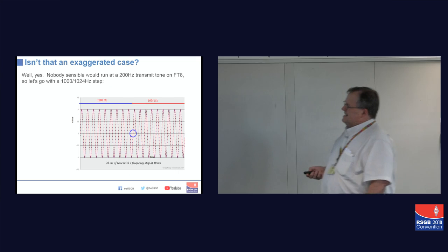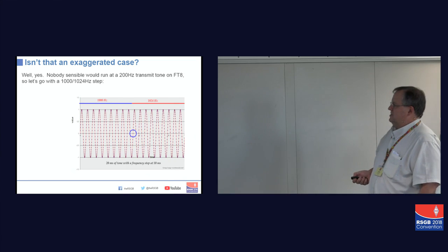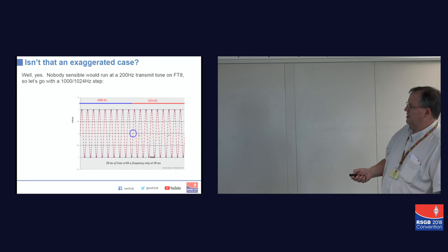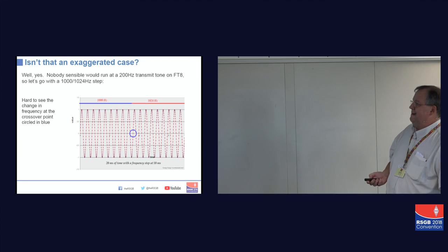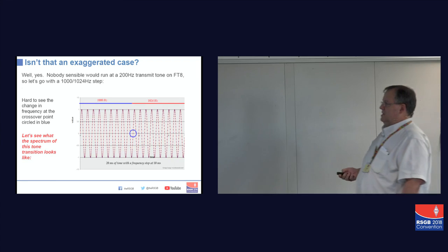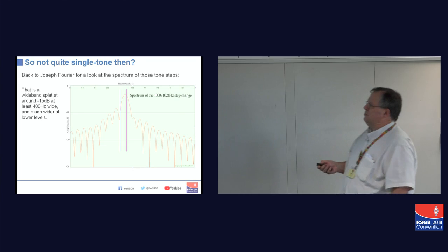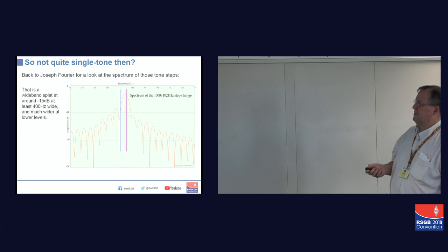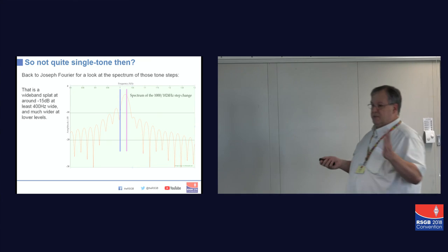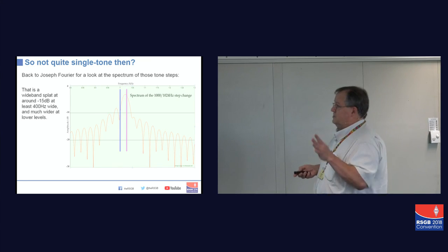Well, looking at that, that's not too bad. It's not obvious that there's any sort of discontinuity. However, once again, if we actually look at what the spectrum is like, we end up with that. And it's a bit of a splat. It's nowhere near as bad as the startup splat, but you're still going to be 400 hertz wide each time the tone changes. So we need to take that into account.